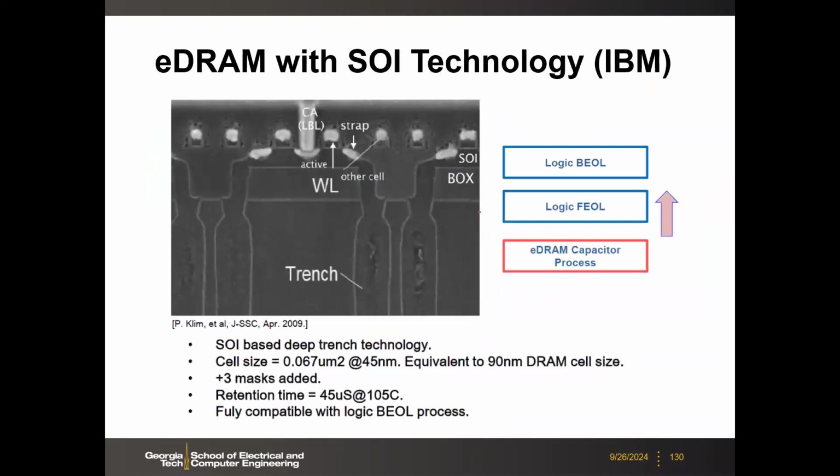So the eDRAM technology was mainly used by IBM in many of their products. For example, here, we mentioned the deep trench DRAM cell capacitor before. And we said it's no longer being used for the standalone DRAM, but still is used for the embedded DRAM. This is true because here you can fabricate this deep trench in the silicon first, and then you fabricate your transistor here.